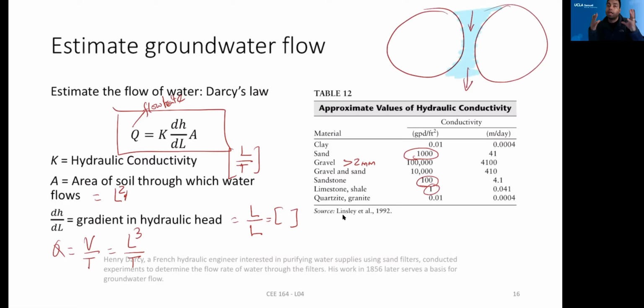But imagine you have two clay aggregates. Clay aggregate means you have to think of there are many particles like this, because clay size is 2 microns or around that small size. So we have a lot of particles like this. I'm just putting a number here. If it is sand, water moves through the large voids. But if it is clay, imagine the same volume, the same size as a clay aggregate, but inside it is a lot of small fine pores. That means it's still porous, in many cases much more porous, but the particles are so close to each other that water itself is tightly bound because of capillary.